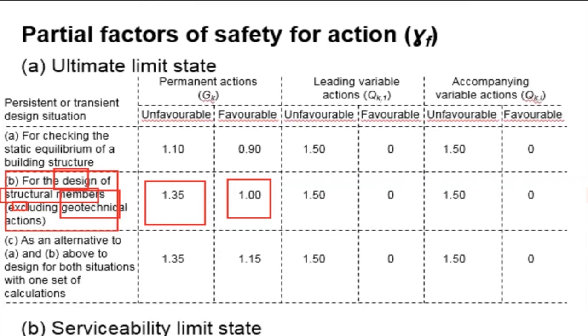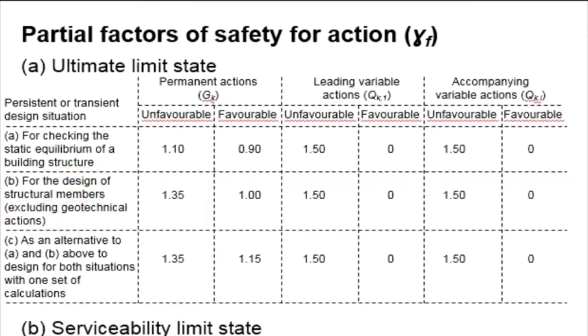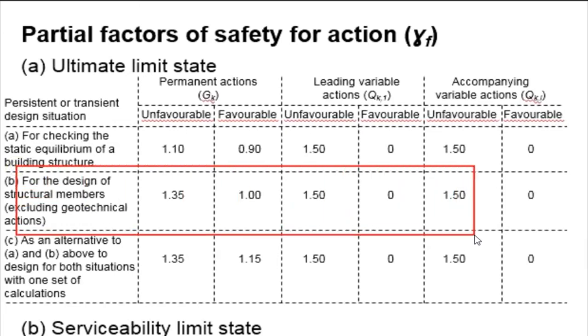Look, here once we consider the Eurocode it is 1.35, but under BS it is about 1.4. The same applies for the variable load: it is 1.5 under Eurocode, under BS it is 1.6. So these are always the most usable conditions for the design.